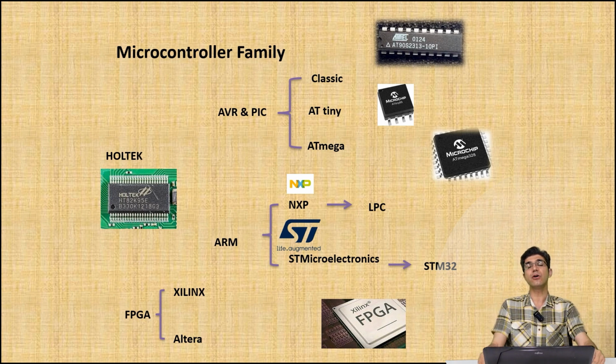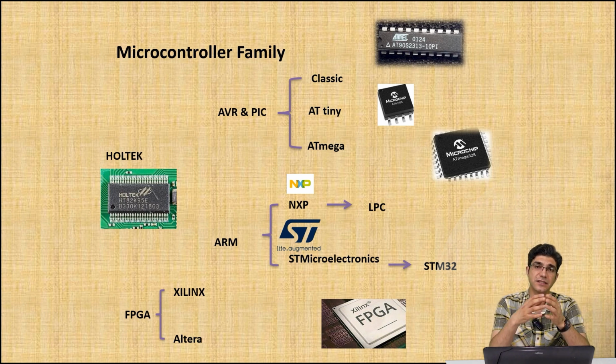The FPGA is like a Lego, and you can make things by programming these Legos, and the application is up to you. But in comparison to ARM it is very expensive because of the technology and because of the pins, and of course you cannot use it individually because they have a BGA package, and you must buy the boards in advance. For example, in designing, you can use your own PCB for your application and your design.